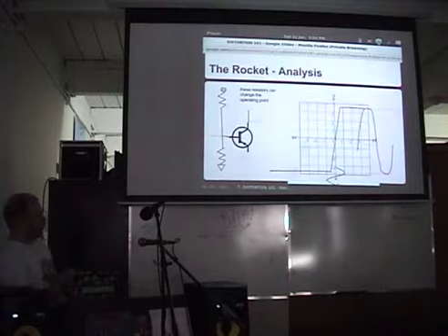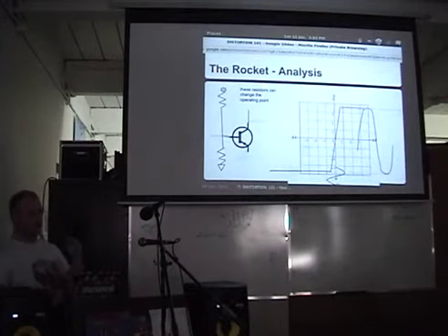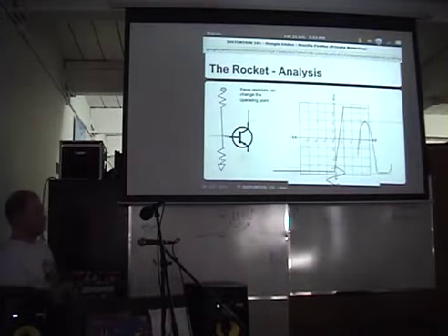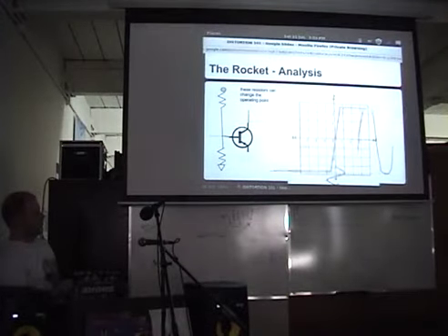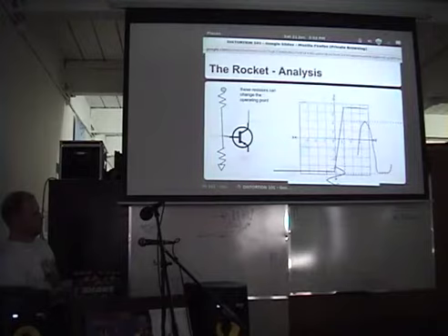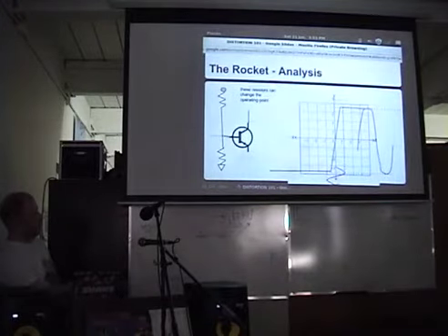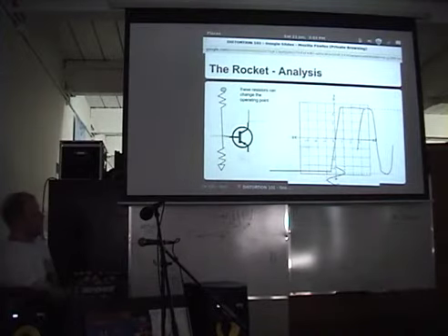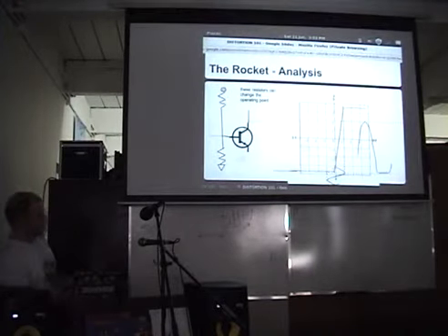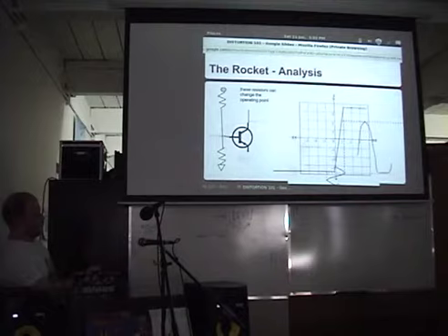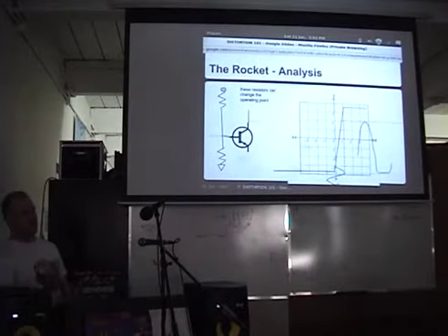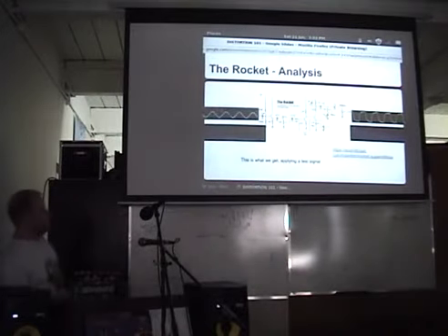For just an intuitive understanding, that's setting the operating point of your transistor, like what its static output voltage would be, which has the effect of shifting the transfer function to the left and right here. We can see we're clipping in both directions here. It's hitting a maximum here and here, but if we shift where it's sitting, it's going to do the full spectrum here and then clip out at the bottom there. Usually it sounds really sucky when you do it that way. It's a thing.